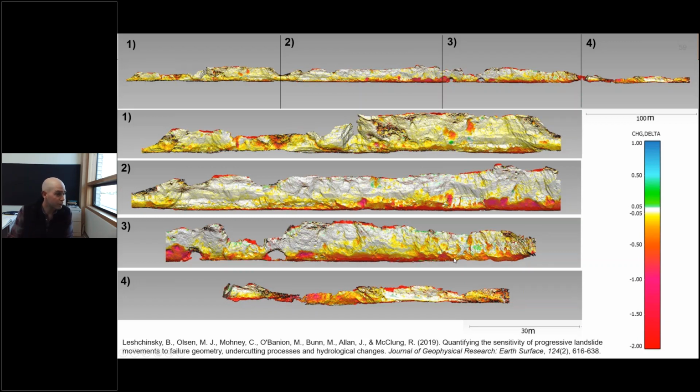And this is what we would expect. The waves come up here and they scour away soft rock constantly. And that material is removed and leaves the sea cliff just a teeny bit steeper. Over time, that can result in larger failures. For example, you can see that there's quite a bit of change here, an overhang failure here, some cliff collapses here. It varies on the site, it varies on the year, it's incredibly variable, but we can measure it.